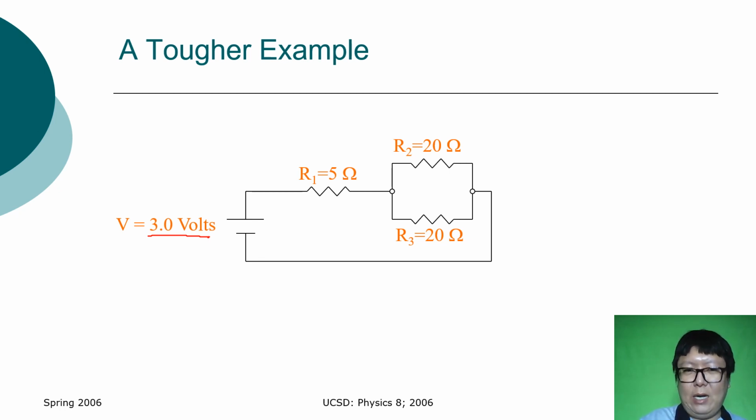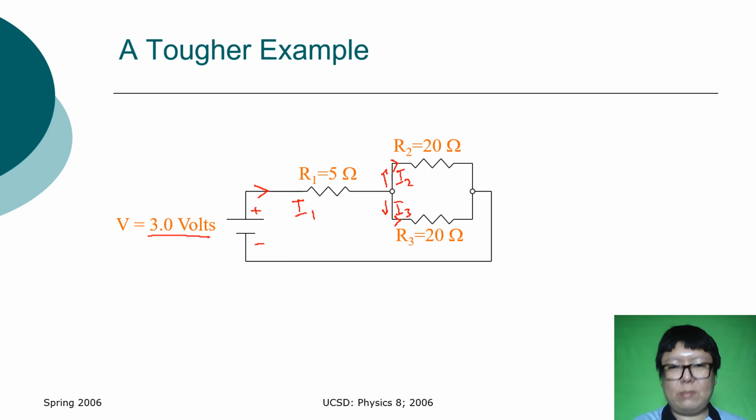As you can see here, how does the current flow? Current flows from positive to negative, so flows here, right? So in R1 only have I. But when it goes to this junction, the current is split. This becomes I1, this is I2, and this is I3. Then in this junction, I2 and I3 are combined again, becoming I1 again, or I total.